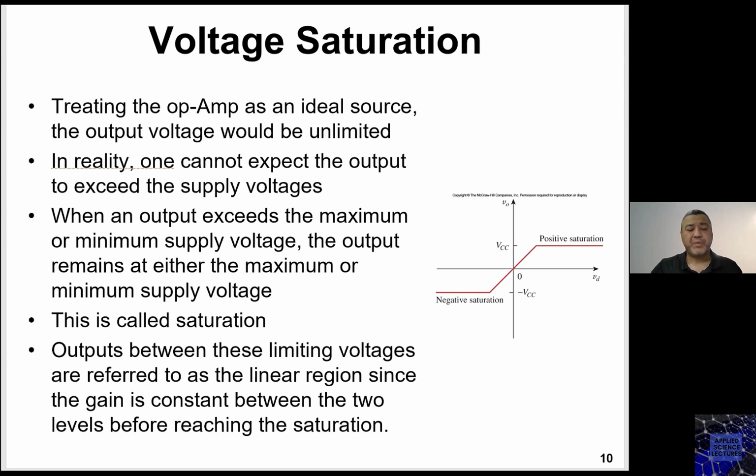Now, what the operational amplifier is going to do is look at the signal that it is sensing at its input, and replicate the signal using its own power supply that you are providing. So look at it as a device that is looking at the signal you are providing at its input without loading, deteriorating or distorting that signal.